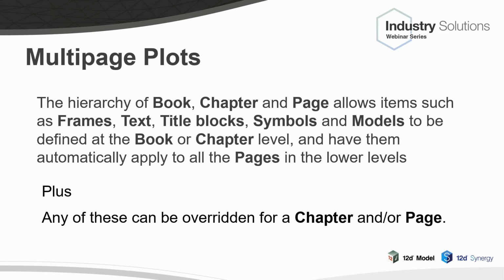The most powerful thing, though, is there are things called references. We can actually override everything for a chapter or a page. So although you've got a title block for the whole book, on an individual page, you can turn that title block off, change information in it, or put a whole different title block. So similarly for all of these things. If you've got a frame on the very first book, so it might be a plan view, that will be there on every view, but again, you can override that on a particular chapter or a particular page. So it's called referencing. So it's very, very powerful. And that's why we've got this hierarchy, to make it much, much easier.